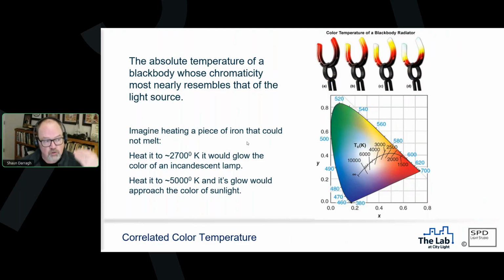So how warm or how cool the light source is, we tend to use these intentionally, right? In a residence or a relatively small space, we tend to use fairly warm light. In larger places, or places that we want to feel very clean and crisp, we use relatively cooler light, say 4000 Kelvin or above. Now, some of this is culturally driven. These are norms for here in Seattle. If we were in Korea, if we were in the Philippines, if we were in some other places, those might not be quite the same. Just understand that there's no hard and fast rule about this.